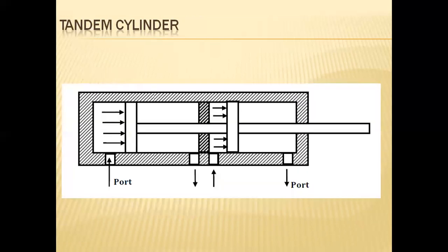There is the tandem cylinder, which works on the criterion that when fluid enters port 1, the cylinder moves forward. Simultaneously, if additional force generation is necessary, fluid also enters through port 1 to port 3 and moves toward the forward stroke.